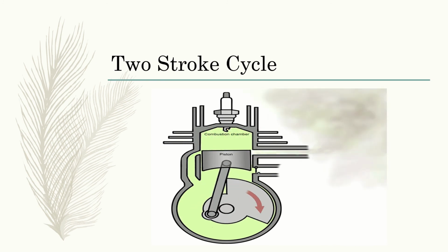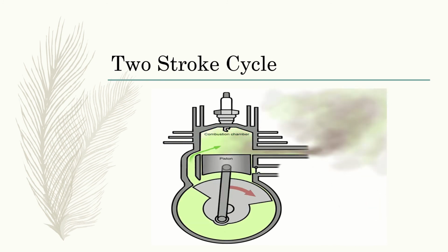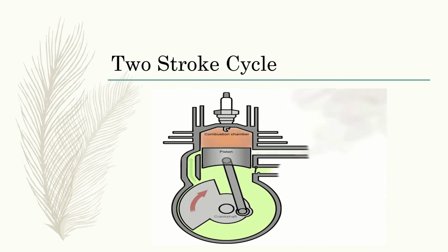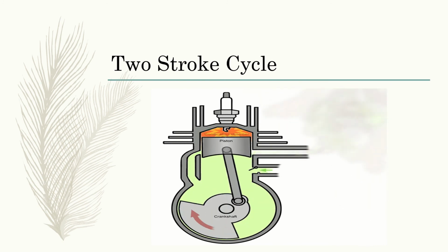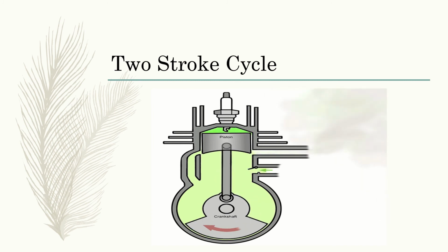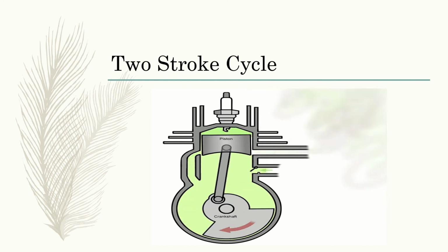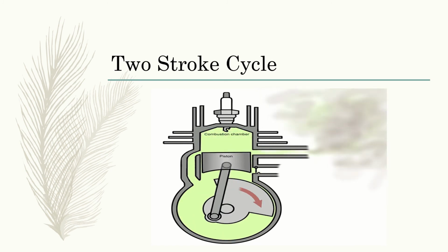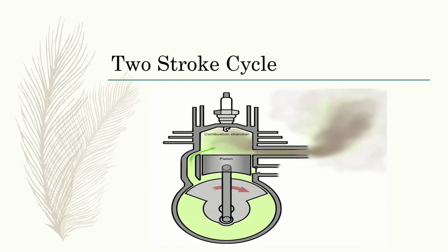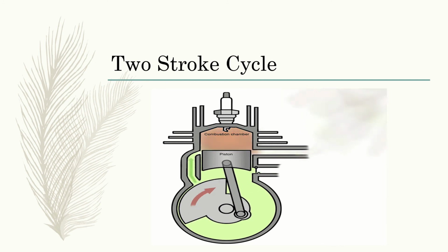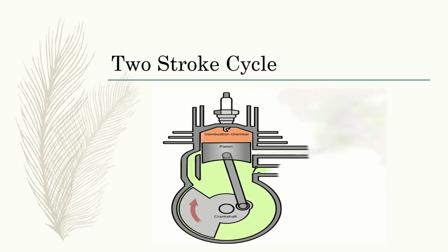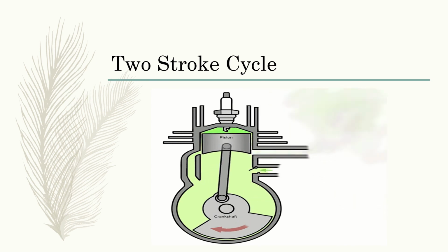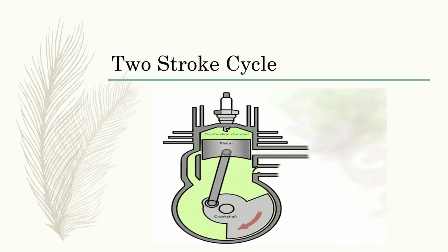On the other hand, four-stroke engines produce more torque at lower RPM, generally provide greater equipment durability than high-revving two-stroke engines, and also provide better fuel efficiency and lower emissions. For these reasons, four-stroke engines are ideal in applications such as motorcycles, ATVs or UTVs, marine motors, and personal watercraft.